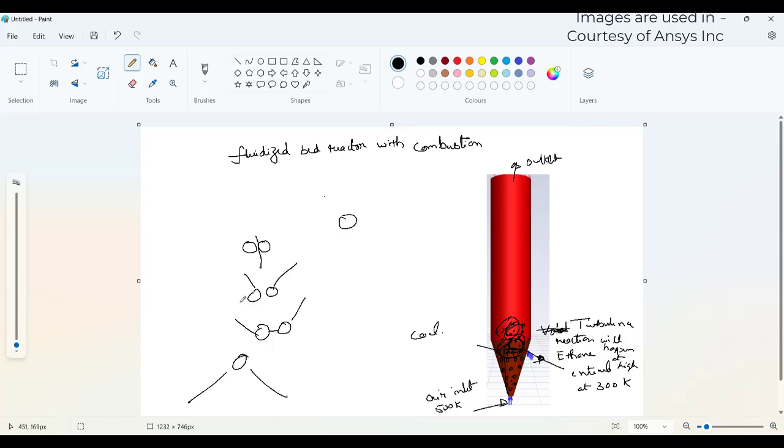It's like two particles coming in from these directions; they can collide and move off in different ways, but not in DPM. In DPM, particle collision is not taken into account, and only through the stochastic or turbulence treatment is particle collision considered.